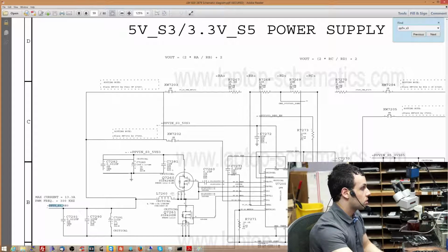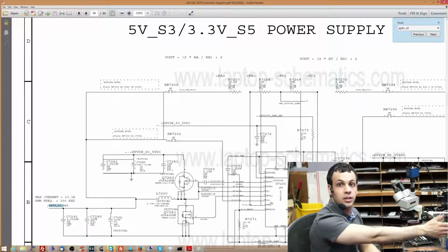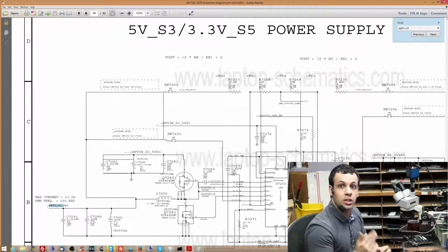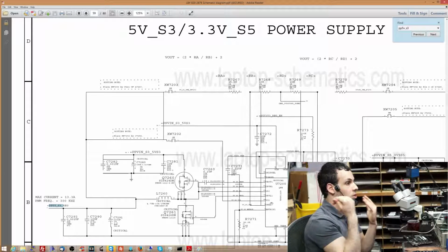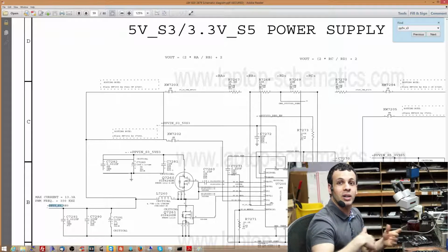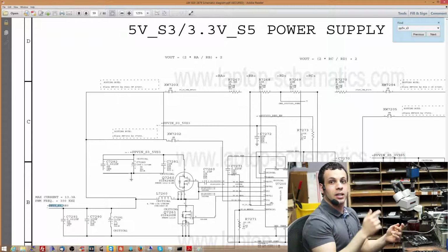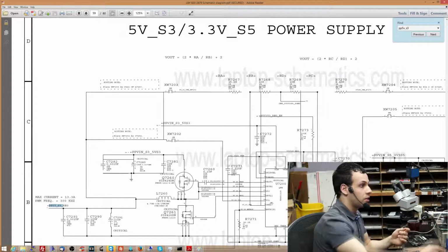So we have two transistors, an inductor and smoothing capacitors on output, and these two transistors are controlled by a controller chip. What does this look like to you? This is a buck converter. And again, you need to be at a point after you're done watching this Introductory Electronics video series that when you see this, it clicks in your head. I don't have to ask you what it is. You see it and you go, aha, this is something of interest to me.